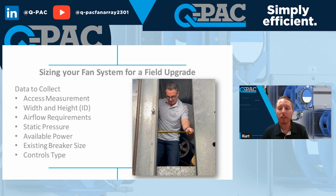Most of the time installing our product is going to reduce the amount of energy that's required for the fan system, which means that you can reuse the existing electrical infrastructure already in place. And so what do I mean by that? If you're replacing a VFD that feeds an AC motor, you can remove the VFD, install our control panel exactly where the VFD was. You don't have to run any new electrical wire or change the circuit breaker. And then you can even reuse the wire that goes from the VFD to the motor inside the unit. Instead, you can rewire that to our control panel and our quick connect box. So it makes the install super easy on the electrical side.